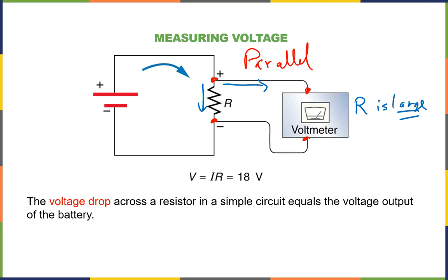We like to use prefixes, so 1.5 kilo ohms. The voltmeter might have a resistance greater than a mega ohm, greater than 1,000,000 ohms. If your voltmeter has a resistance that's 1,000 times bigger than the resistance you connect it to, it's 1,000 times harder for charge to go through the voltmeter. You're not going to have anything go through it effectively, and that's the goal.